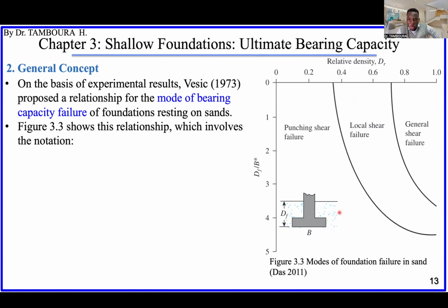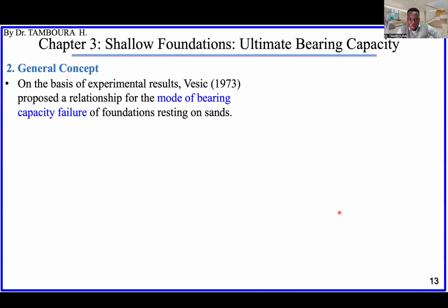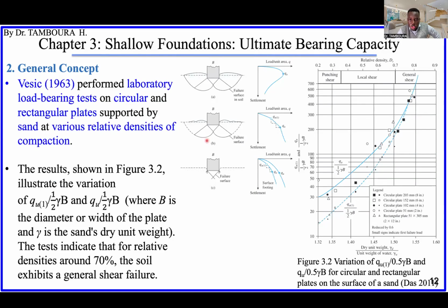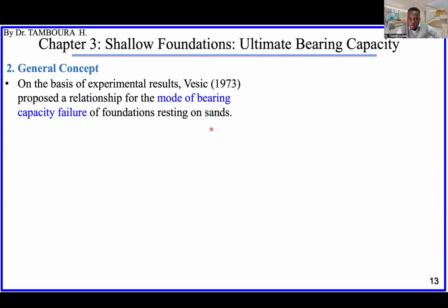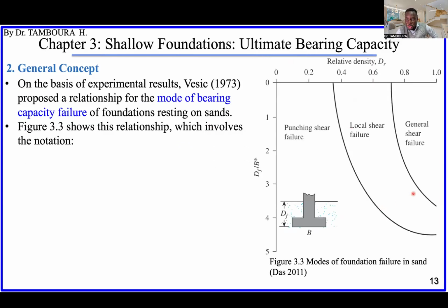That is the problem. I will go back to show you what I'm talking about. You can see the general shear failure, these lines are going up, like this, up. But if it is too deep, this footing is too deep, it cannot reach up easily. So it will be around here or even here. This type of failure or this type of failure will happen. That's the problem when it is too deep.